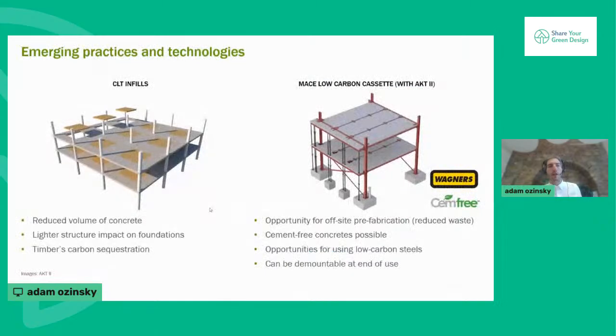Very briefly on innovation. These are some of the things that we're seeing in our practice, some of them quite a lot on projects. So CLT infills, or precast concrete infills, so trying to displace material where the material is not working so hard. We've got a number of projects where we're looking at doing things like that. So a reinforced concrete frame, and then in the middle of the bay, as you can see in the little diagram over here, adding a CLT infill perhaps, or even a precast concrete biscuit.